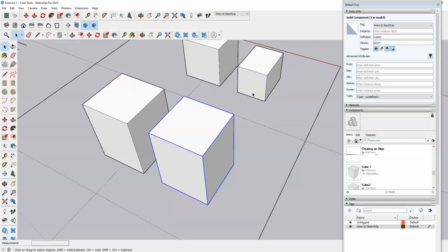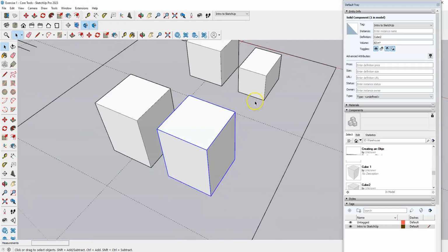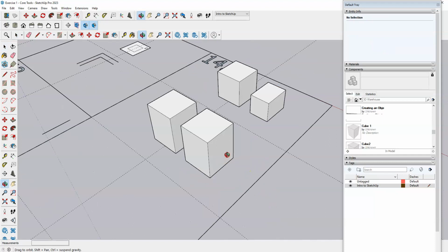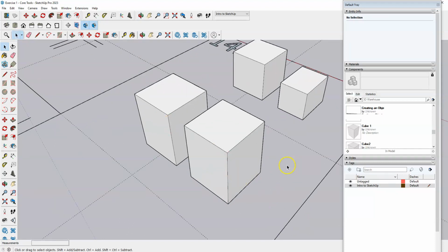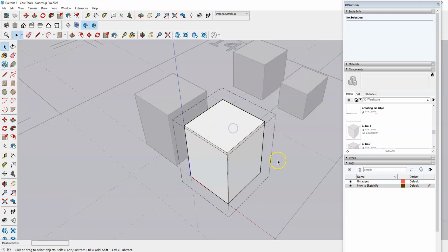You can always come up here and change the name of that or the definition of that. Yes? I forgot to do the push pull, there's a button that I press. Like you can't find the push-pull tool? Yeah, so what I think might be happening, if you try and use the push-pull tool, but you're not inside of the component or the group, it's not going to let you edit it until you double-click into that component or group, and then you should be able to edit it.